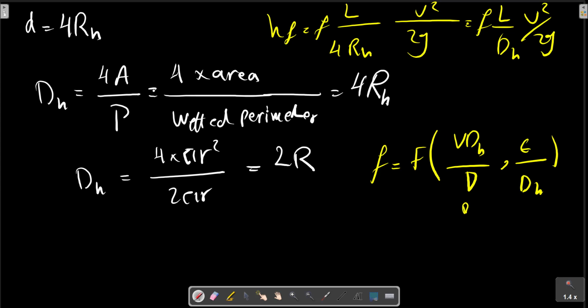These two nondimensional parameters are well known, and this is the way that the data are correlated, but we should not necessarily expect the Moody chart to hold exactly in terms of this new length scale.